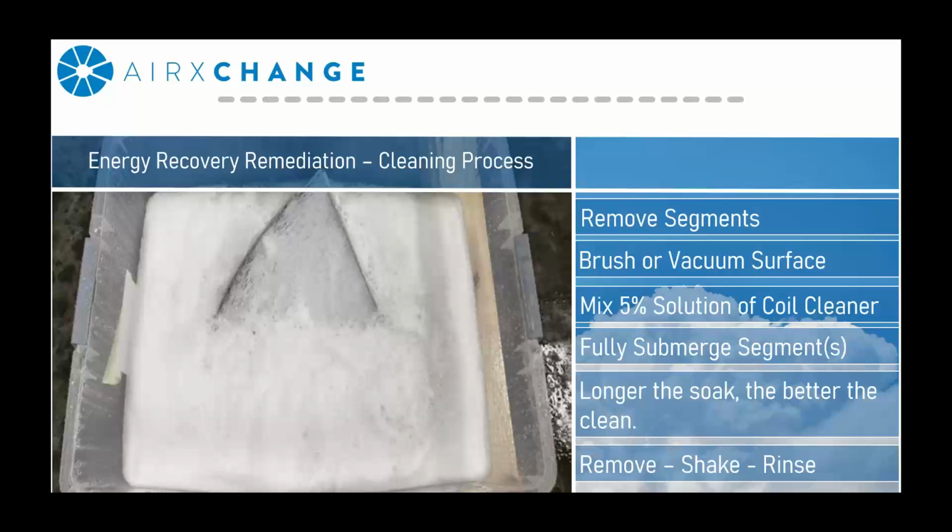By fully submerging the segments in the solution, it allows the cleaning agent to fully penetrate the heat exchanger surface area. The best way I can describe this is, you remember those old Dawn commercials where they put the dirty dishes in the sink and stuff starts lifting off them? That's essentially what you're hoping to accomplish here.